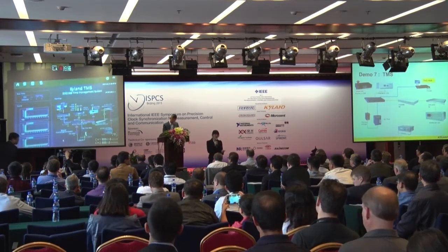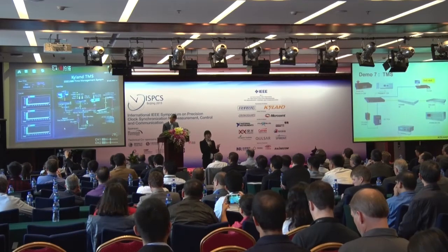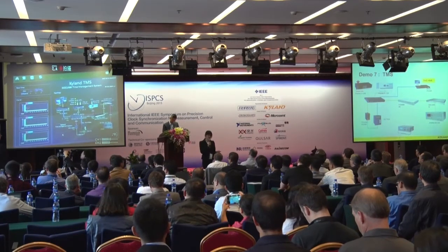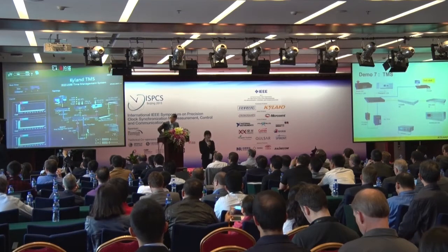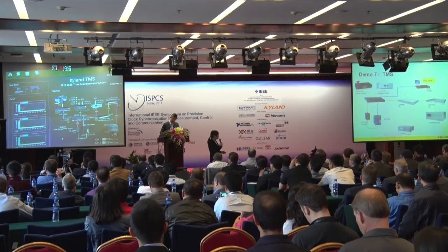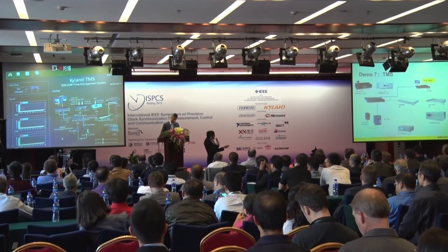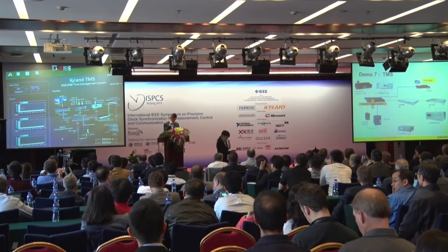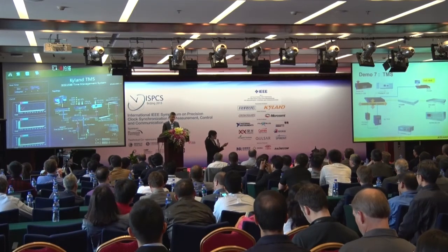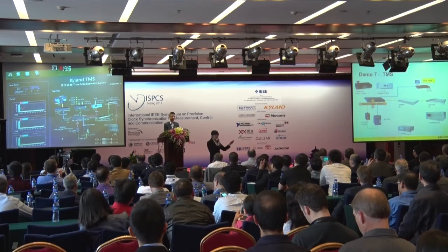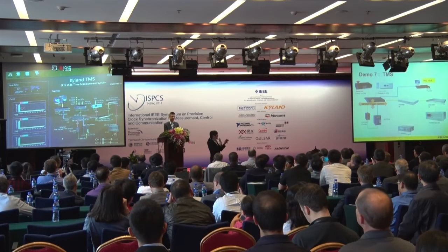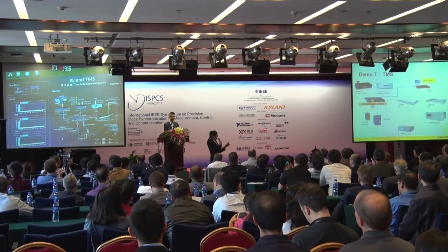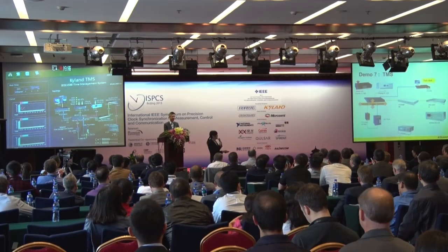For those unpredictable events which cause out-of-sync events, sometimes we have no measurement for these end devices. So in our TMS solution, we are using a GPS trigger module, and this GPS trigger module is already synced with the grandmaster clock in the system, and publishes the GOOSE messages into the system.